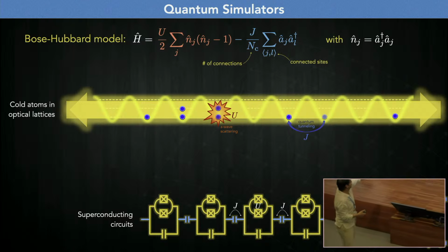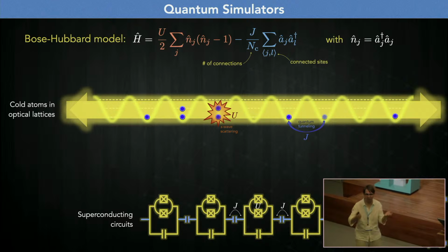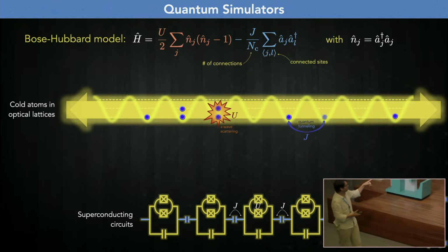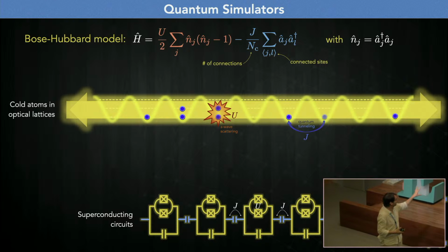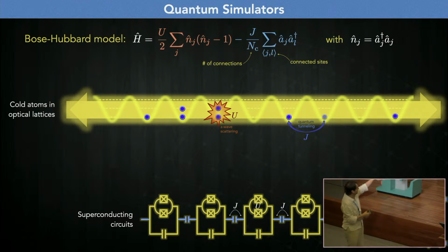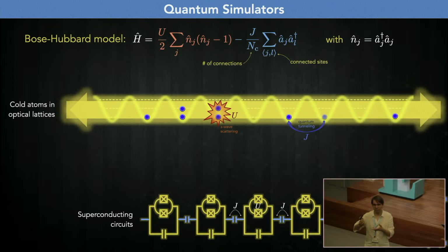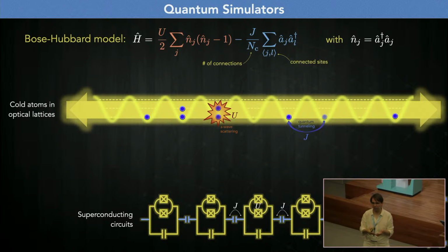You could just replace the inductor by one Josephson junction, and it would also create a nonlinearity. These two junctions in parallel are also interesting for one reason. It's the one I use when I do theoretical models, because this makes the system sensitive to the magnetic fields that go through the junctions. The magnetic flux in this closed circuit changes the physics of what's going on in there. So then you can use an external magnetic field to drive the system, for example. You can couple your circuit to an external magnetic field that you can modify at will.